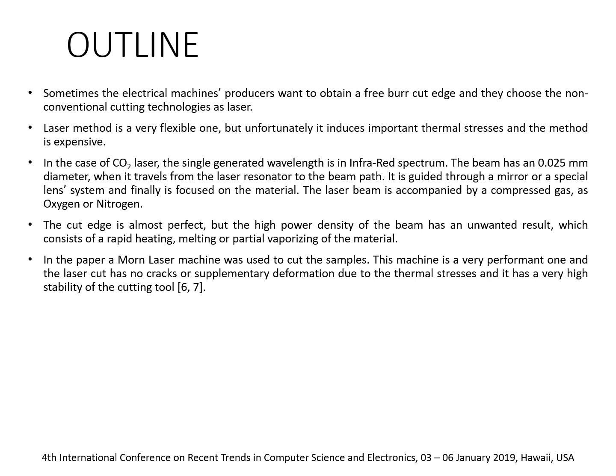The beam has a 0.025 mm diameter when it travels from the laser resonator to the beam path. It is guided through a mirror or a special lens system and finally is focused on the material. The laser beam is accompanied by a compressed gas such as oxygen or nitrogen.